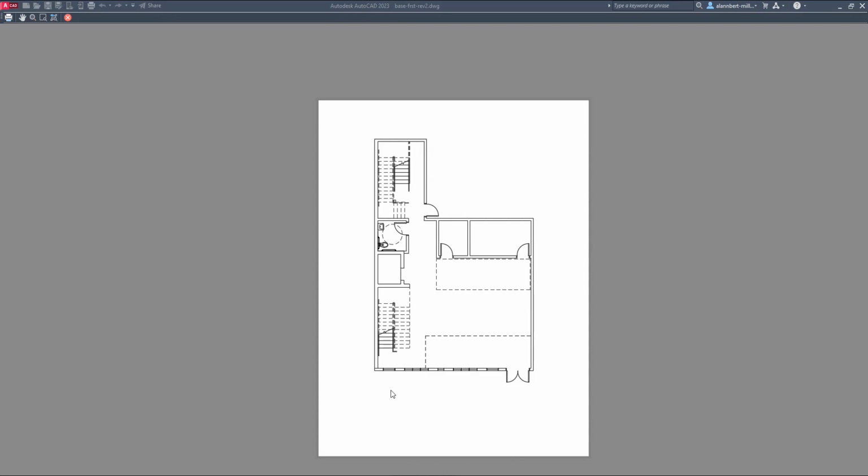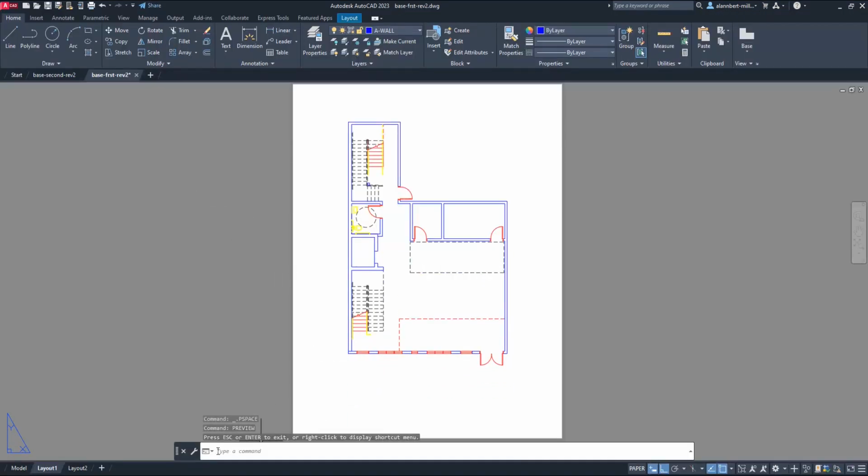So I'm going to cancel, click the X, and then go back to paper space, and we're just going to select, I like single line, so I'm going to do a single line text, and I'm going to put in a text height of 1/4, and then the angle is 0, and the name of this one is